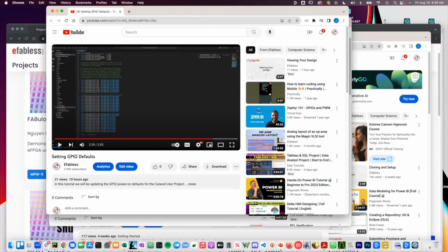So it's a 32-bit RISC-V microcontroller, and it is possible to target 32-bit RISC-V using TinyML today. It would be hard and not super high performance. I would suggest that if you're going to do an ML load today, it would be interesting to build an accelerator to do it rather than trying to run it through the CPU. But you should be able to target a RISC-V CPU from the TinyML software stack today.